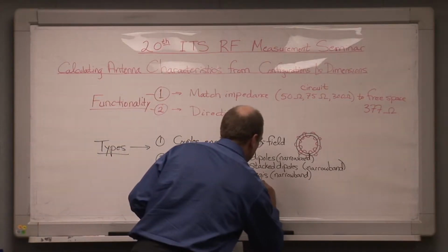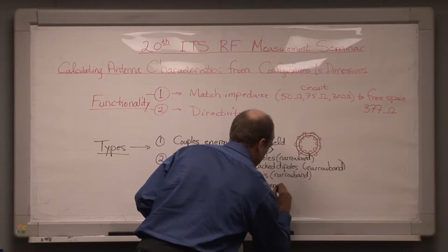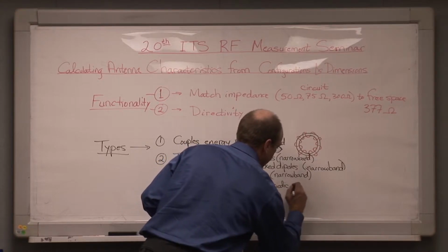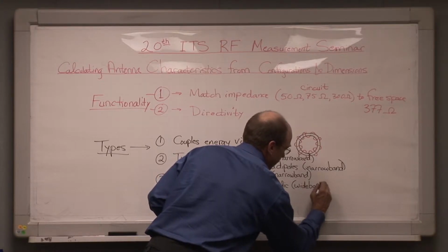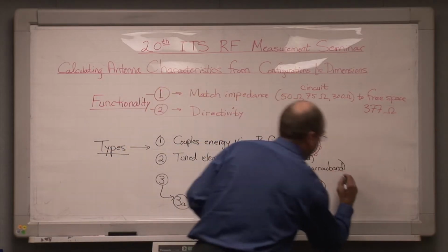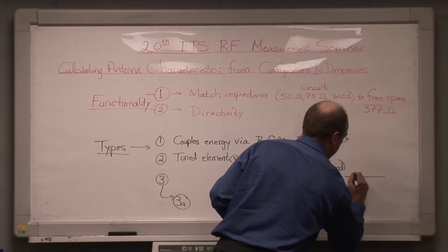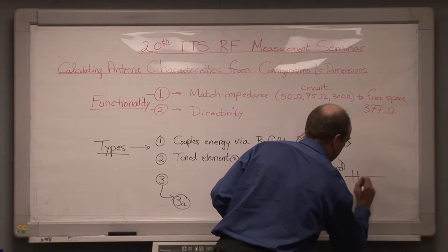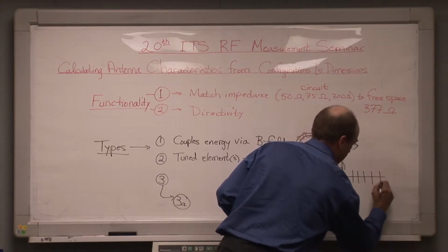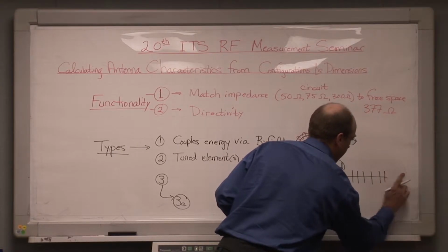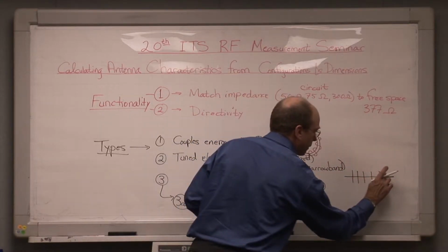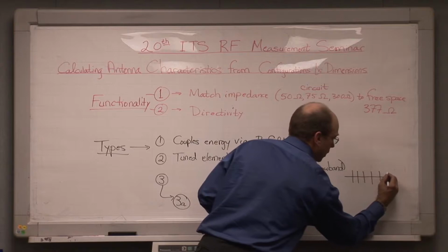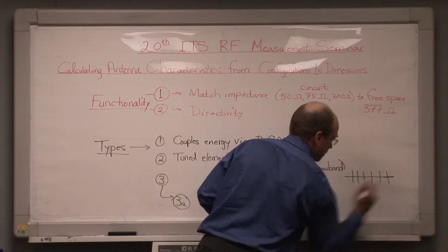And then finally log periodic antennas, and these are by definition wideband. And the reason that they're wideband is, unlike a Yagi antenna, which if you see it will look like this, seen from the top or seen from the side, in which the element size and the spacing between the elements, which I've tried to draw as a constant, is adjusted for a single frequency.